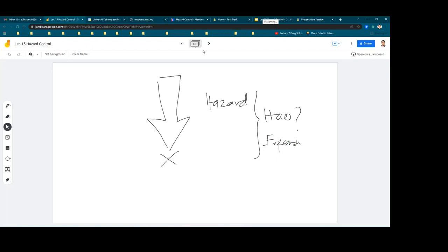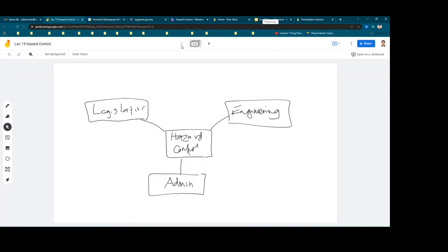So this will be the roles of the engineers, especially safety engineers, chemical engineers, process engineers, design engineers, to ensure that the hazards of the process have been reduced as low as possible. So that's why in engineering it will involve these three hazard control. If you read the slide, there are three principles on this engineering control. First, normally we do the enclosure. Second is isolation, and the third is ventilation.